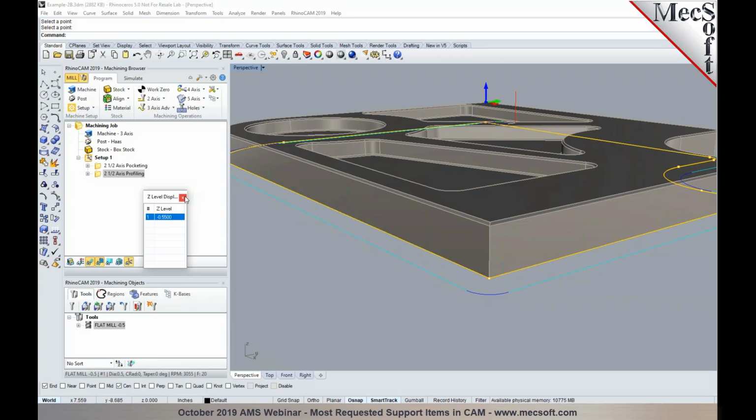Now, if you had selected at bottom, then you wouldn't be able to cut below this region unless you actually move the geometry physically in the CAD. So the location of cut geometry gives you the ability to adjust the Z-start location of your cutting without having to physically move the geometry around in your CAD system.